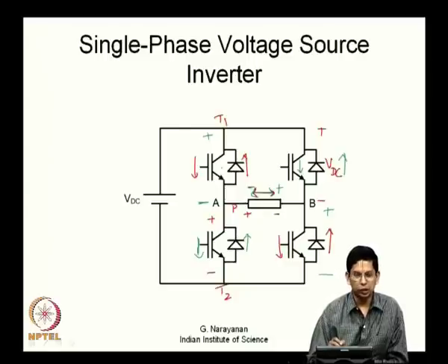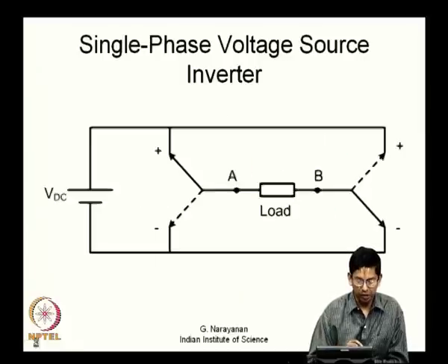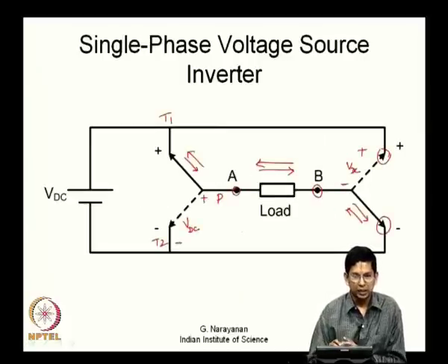Similarly, if the pole is connected to throw T2, you needed a bidirectional current carrying capability which you have here, and you wanted the top switch to block a potential with polarity T1 being positive with respect to P, which it does now.